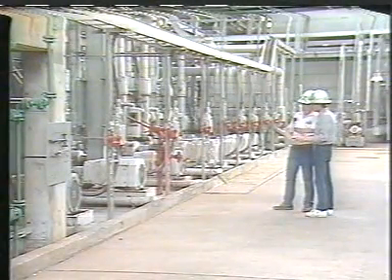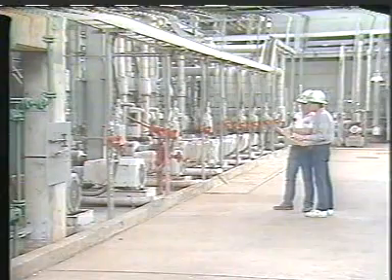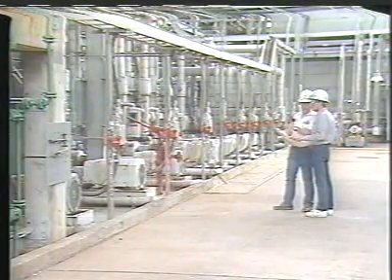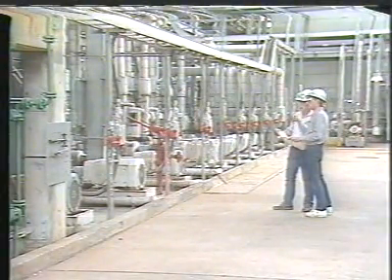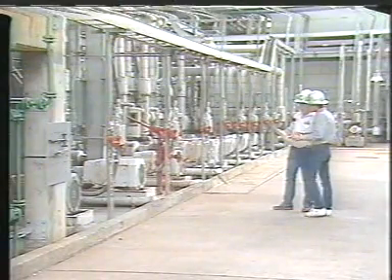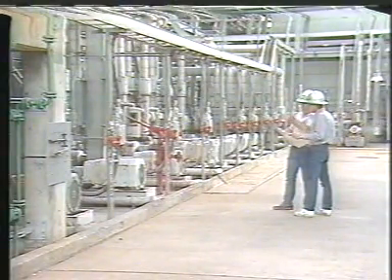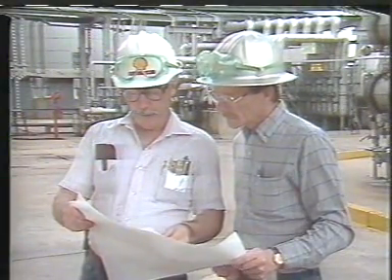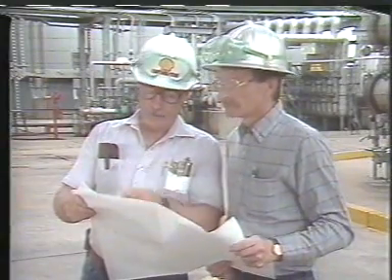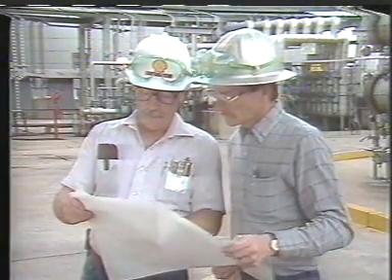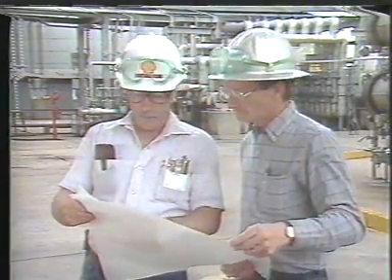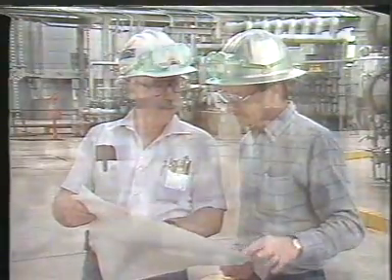Because it is difficult to tell precisely when a mixture of air and hydrocarbon vapor reaches the explosive range, it is best to completely avoid mixing hydrocarbon vapors with air. In shutdown operations, all hydrocarbons are taken out of the tower before any air is let in. And during startup, all the air is taken out of the tower before hydrocarbons are introduced into the column.